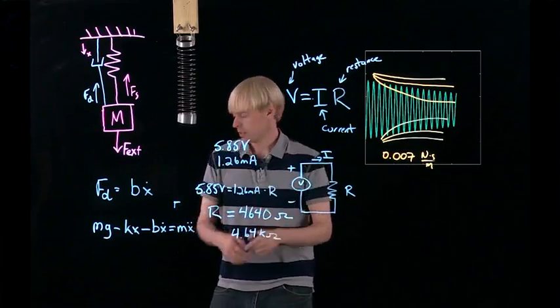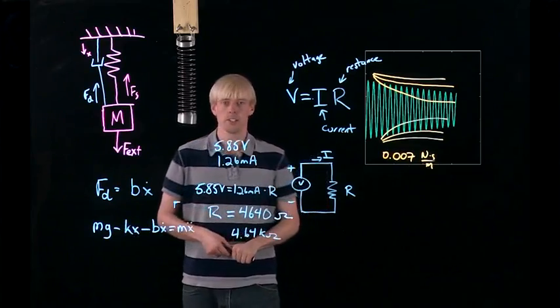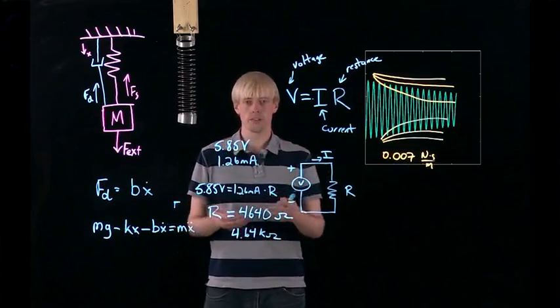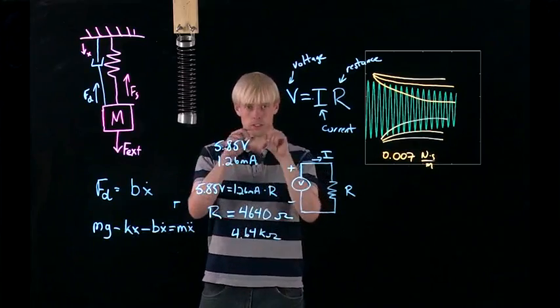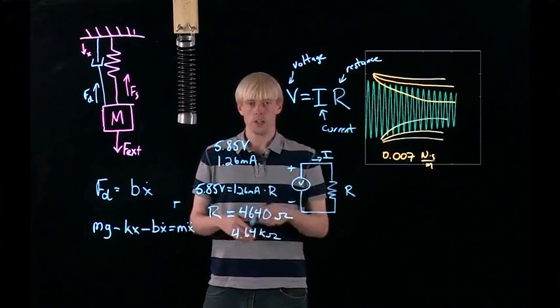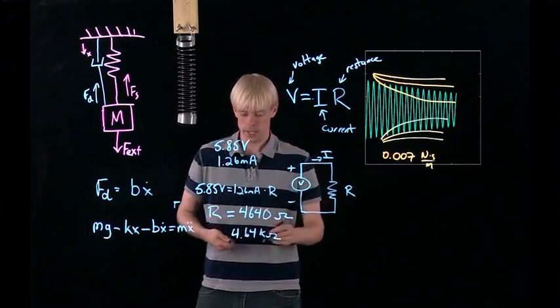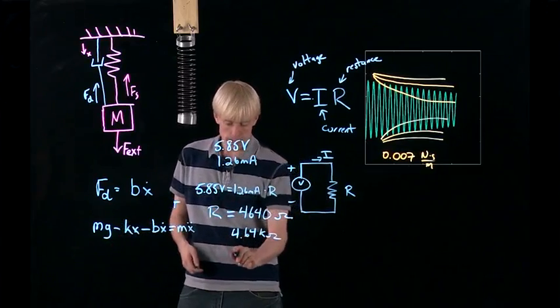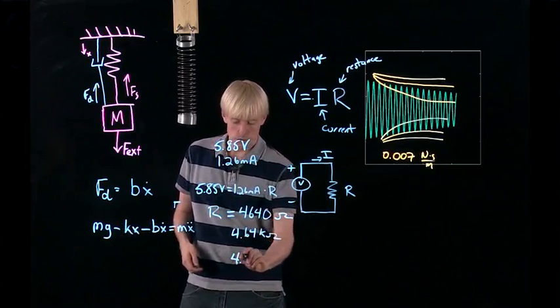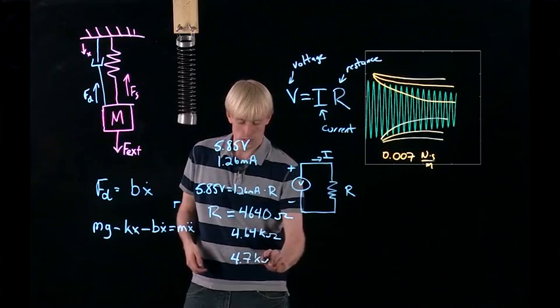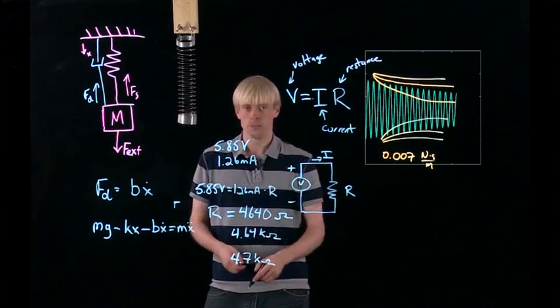So how do we check whether this is right? Well, fortunately, resistors have specified resistances on the resistor themselves. They're the little color bands on the resistor. You can look on the internet for how to read those. And I read this off, and the specified one is 4.7 kiloohms. And that's what the resistor is rated for.